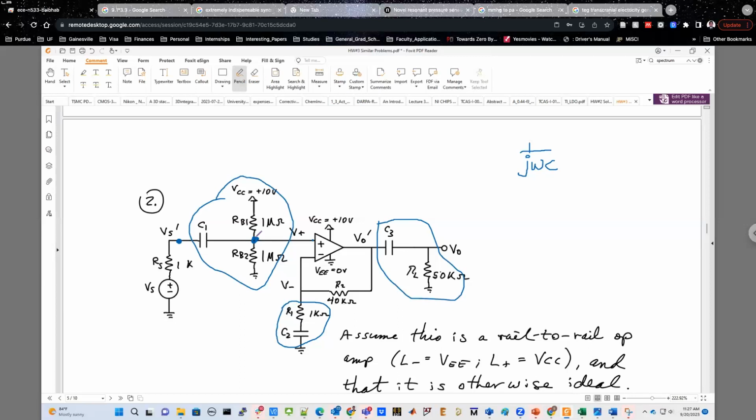So it's better to isolate, it's better to decouple those two DC voltages, and that you can do by putting a capacitance over here. People who have worked with audio amplifiers, I think you already know about this stuff, but this could be new to some of you. This is how you isolate different DC voltages or DC points. Similarly, at the output side, if you put this capacitance, you'll isolate whatever DC voltage you want to develop at the output side versus whatever DC voltage you develop at the output of the op-amp. So again, this capacitor just isolates the DC points or the DC voltages.